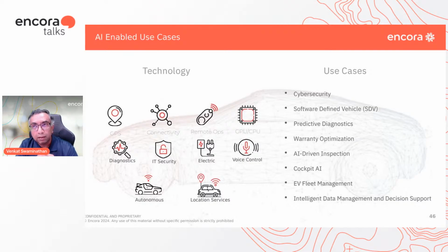Diagnostics is a key thing. Not all of the data that's flowing through a car has to be useful for something. So what's happening is, as you're able to bring in edge AI or push machine learning models into the edge because of the compute, network and data bandwidth available now, you can run diagnostics on the edge. Rather than just giving you an error code or the check engine light turning on, the car can be a little more proactive and say, I think you need to go into a dealer, have this looked at, and the dealer can pull up more information. Looks like the oil temperature was a little too high over the last few drive cycles. So what does that mean?